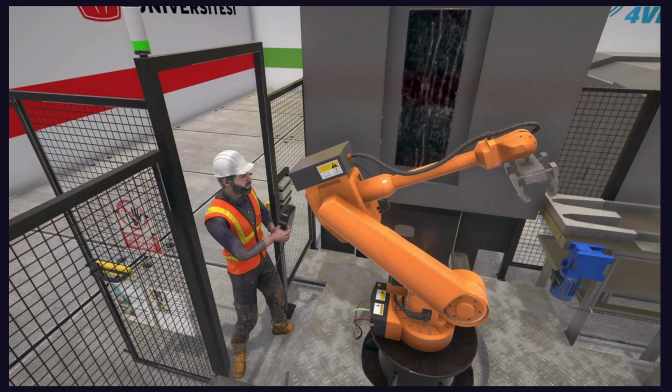During programming activities performed using the teach pendant in manual mode, where multiple individuals need to be present within the limited area, each person should use a 3-position enabling switch, enabling device, to ensure that robots' movements do not pose a danger to others.